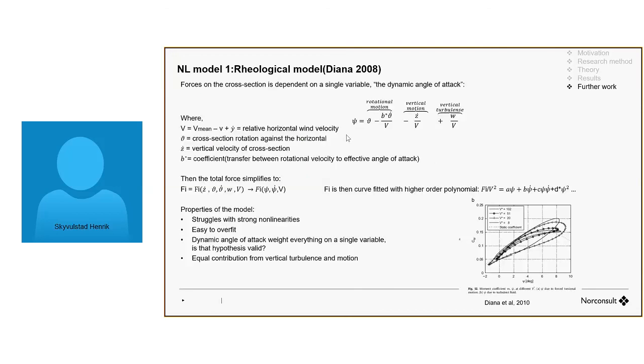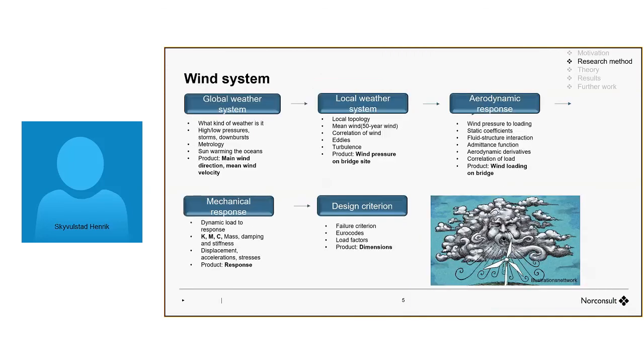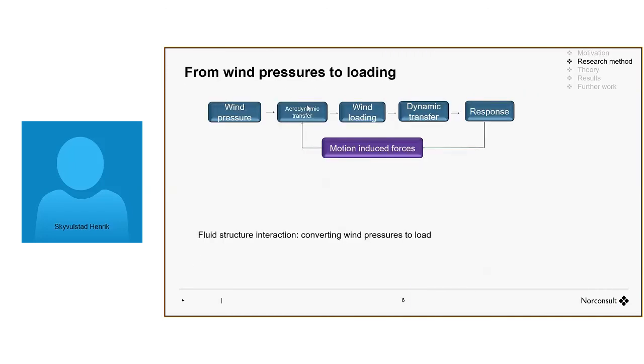Yeah, I can show you. Maybe that's easier. Okay, so here you have wind pressure, and then you have a transfer function, and then you have the response. But if we consider a wide range of wind pressure and actual motion, and train it on this, it doesn't matter what kind of dynamic transfer function we have, as long as it's inside the training bounds. And then you would validate it with a numerical model, like the normal analysis that we do for bridges, for example.